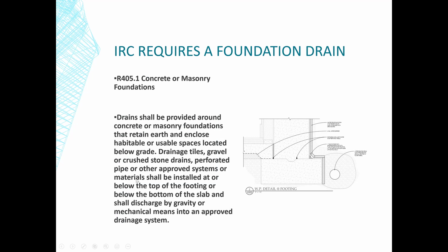Perforated pipe installed at or below the top of the footing. So it's definitely at or below it. This is below. Or below the bottom of the slab. So if we raise this slab up, you could have this pipe be up here if this footing dropped really deep. There's the point.